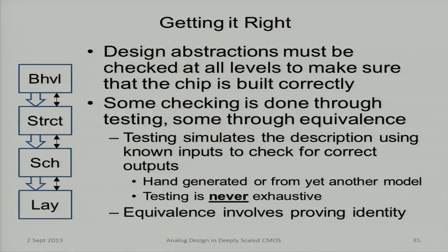And so some checking in general, when I say checking, I mean I compare one abstraction level to the next. So LVS compares my layout to my schematics and makes sure that the two match. In general, my checking techniques can be equivalence checking or they can be testing based. So equivalence checking, when I compare layout to schematics, I actually extract structures out of the layout, compare them to the schematics, one for one, make sure they match identically.